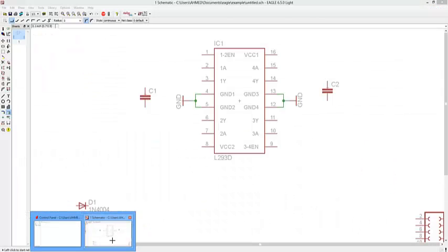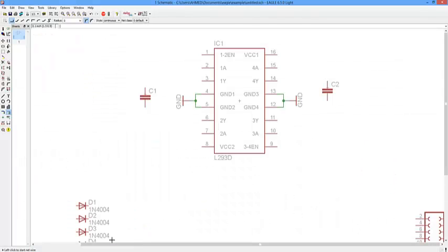So why are there two VCCs? Simple. Inside you have two circuits. You have the logic circuit and you have the motor drive circuit. Now to drive the motors, obviously you need a separate supply for them. Maybe your microcontroller or Raspberry Pi, for example, only uses 3.3 volt logic. So it's impossible you're going to drive the motors with 3.3. So a separate VCC is made for them, so you can drive them at whatever voltage you want and control them with a weak input voltage. So this one is going to be 3.3.